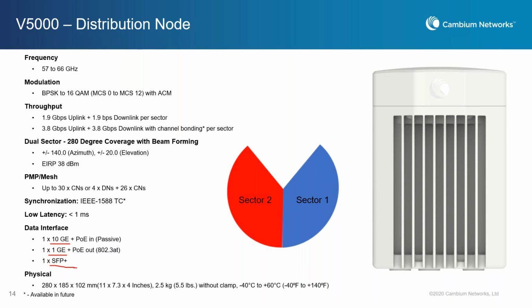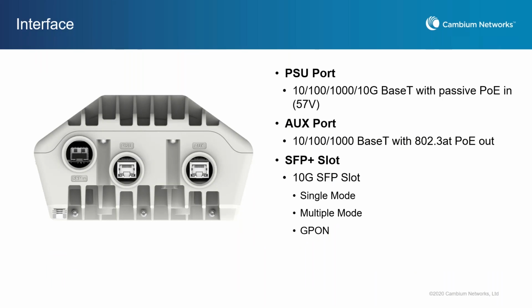Back to the previous chart, what we're saying is because we're doing 2 sectors, we do not need any site routers to pass the data. And in most designs, we expect a single radio per pole, because when you really form a mesh, the radios need to overlap with each other. So even though we have this 80-degree gap here, we really don't see this become a problem in the field. Instead, think about the obstruction, the pole mount you have behind you, or the wall behind you. This has a pretty good balance between the coverage, and a single radio per pole simplifies the installation by a great deal.